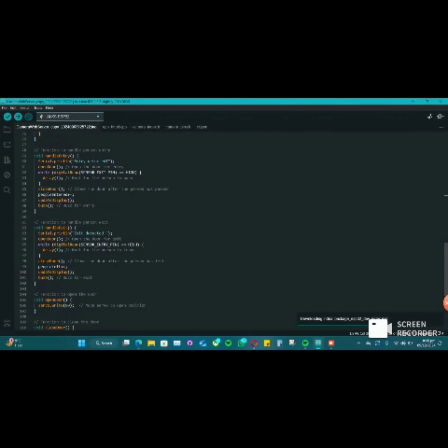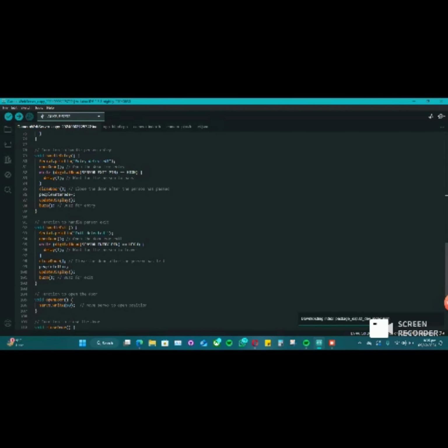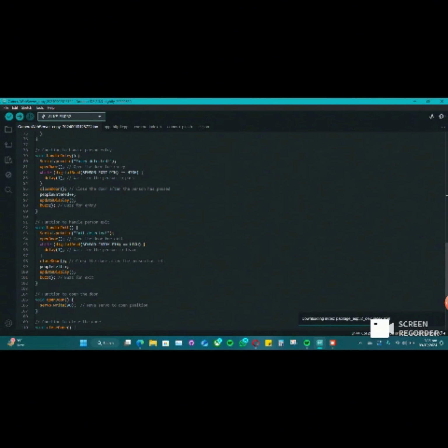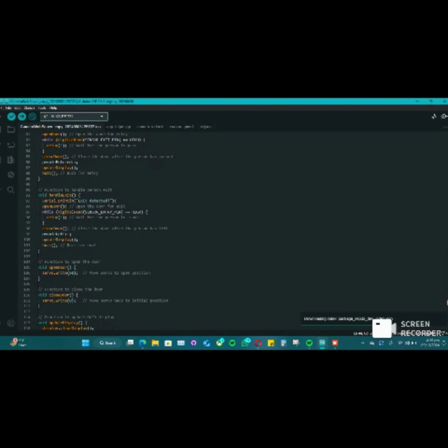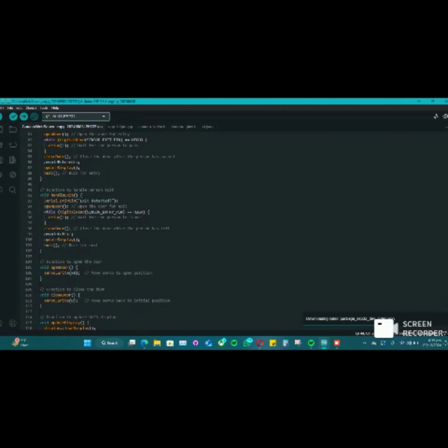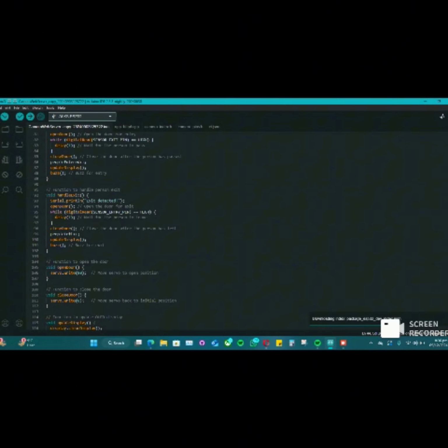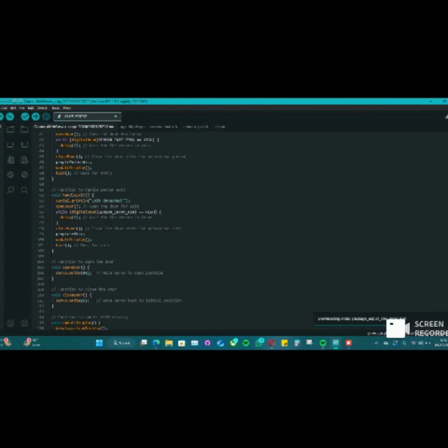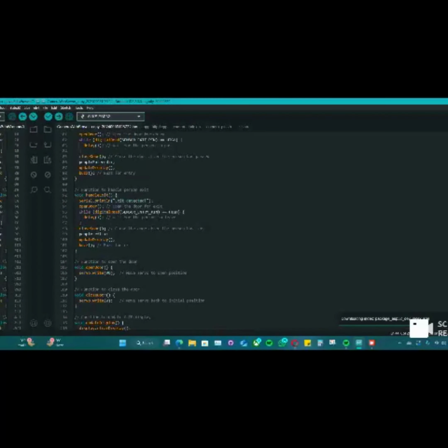The entry counter is then updated and the buzzer sounds in order to show that the person has actually passed and will later be leaving on the exit sensor, which will then again close the door, and the count is registered on the OLED display as person entered and then person leaving, resulting in a complete count.